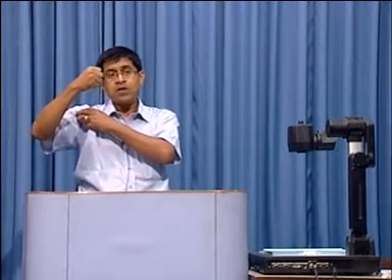On the other hand, I am here and I would like to know how much these two joints must move to go from here to here. That is my reverse problem, or the inverse problem, and it is required to control the robot. As human beings we know very well where A is in Cartesian coordinates, and where B is, but ultimately I achieve point A or point B by rotating these motors. So, I calculate this. That is my reverse problem.